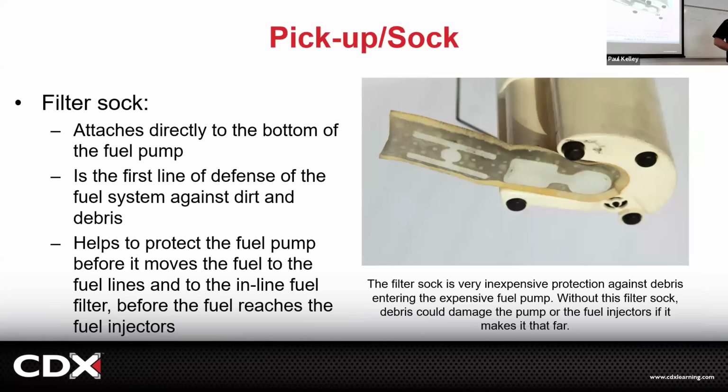So let's say we're working on our pump. Here's the sock. If this thing was all full of stuff, what do you think the symptom would be? Low volume. Low volume, exactly. See, I could test that with the gauge. What do you think the customer's concern would be? Low power on heavy acceleration. It might idle good. If you accelerate a little, it's good. But if you punch it wide open, it's like, I don't have enough gas. You see what I'm saying?